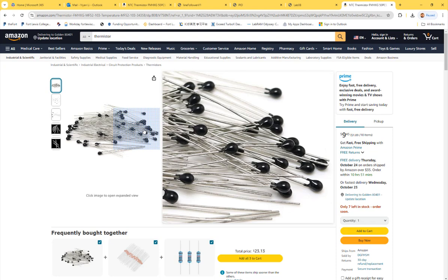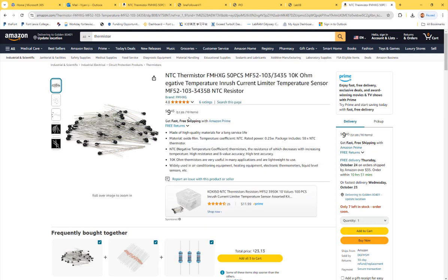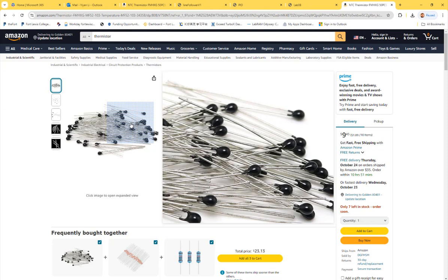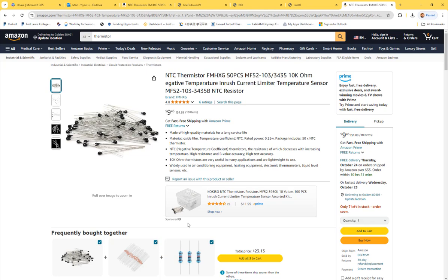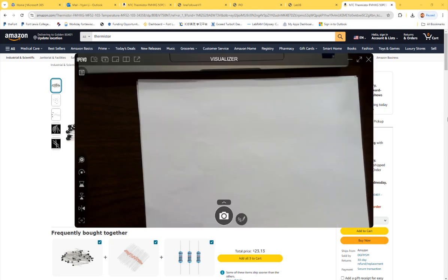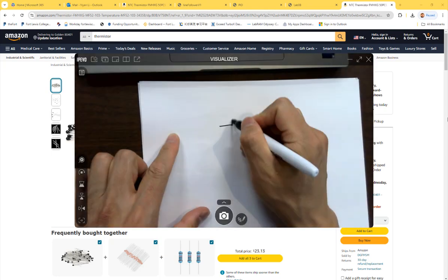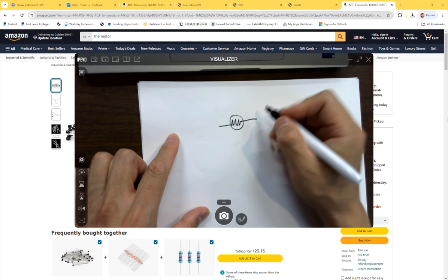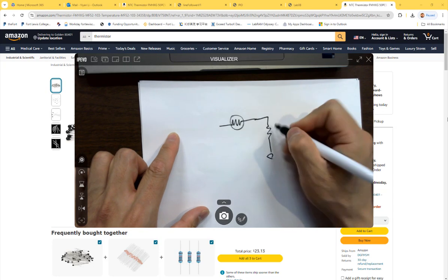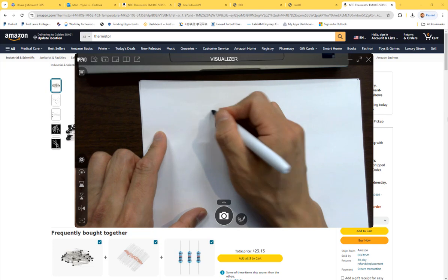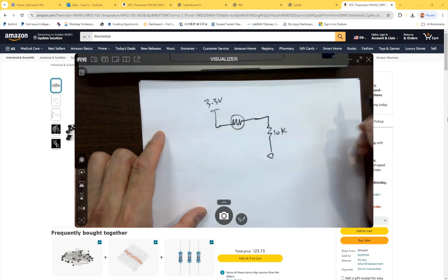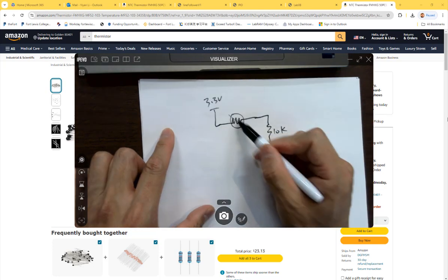Super low cost temperature sensor you can get. So temperature changes, resistance changes. Okay. So given that, how could you get a temperature out? So you send a current through them, or you set a set voltage across them, and then you measure the current that you're getting. So you know the resistance of the component, but then you use a table or a formula to figure out the temperature. Temperature changes, this changes, right?